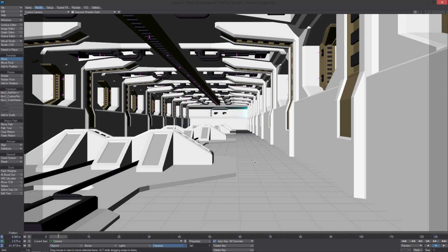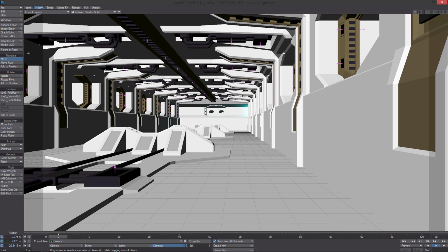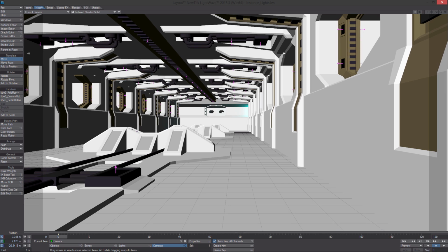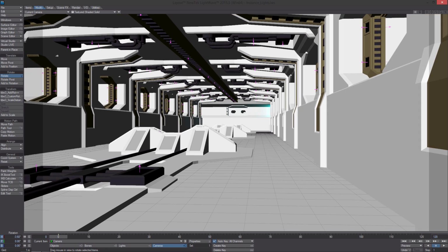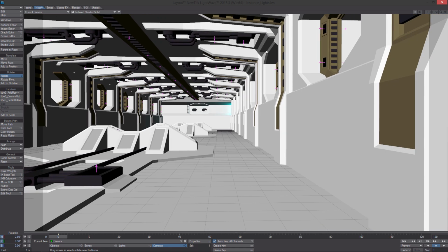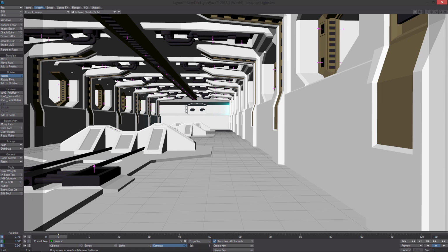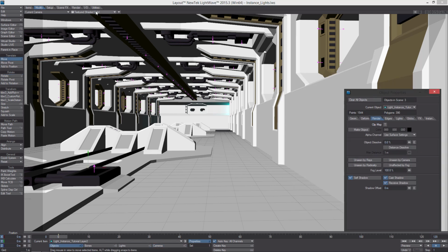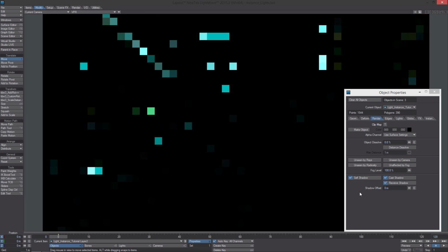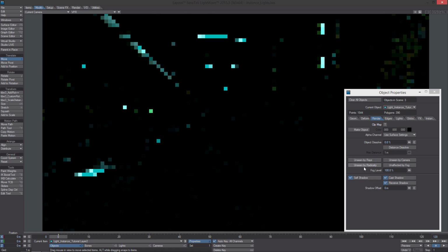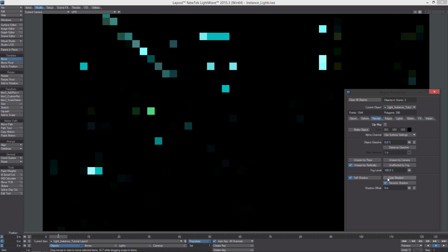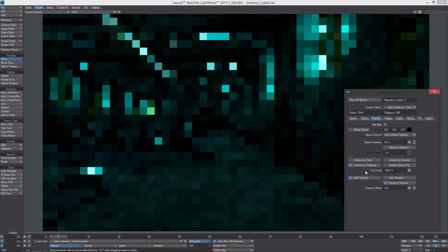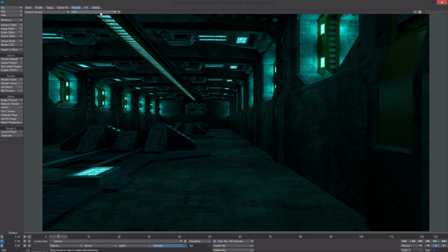So now I just loaded that other geometry in. That was the lights themselves, the luminous geometry. And I moved the camera up. So now there's luminous geometry where the lights are. The lights are sitting a little bit behind it. So the only thing we have to do here is, you'll notice when I go into VPR, you won't get anything. So what we want is, we don't want that luminous geometry to be seen by radiosity because it's not necessary because there's lights there, and we don't want it to cast a shadow. I let that go for a good bit just so you can see how it cleans up.